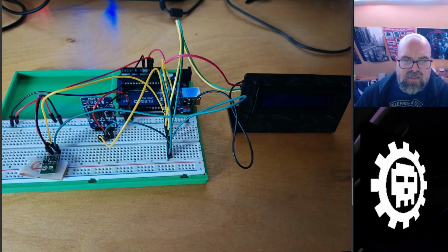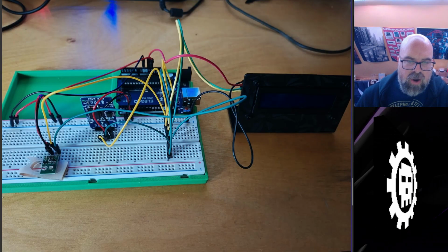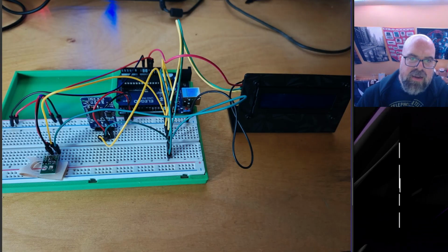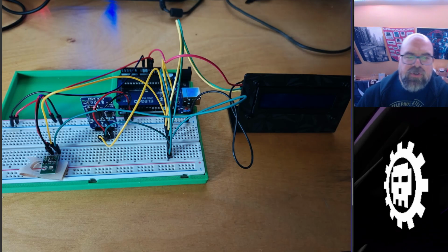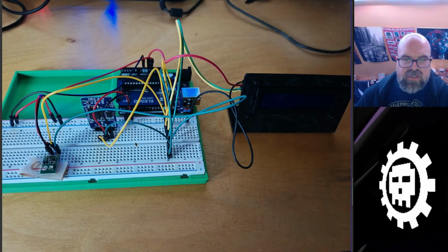Each of these devices is hooked to these yellow and green wires. The yellow wires are for the serial clock. You can see there's a yellow wire plugged in right here at the end of our Arduino, the serial clock. That is plugged in to this row of tie points, and then we have a yellow wire going over here to the LCD. We have one going over here to the temperature sensor, and we have one going over here to the real-time clock unit.